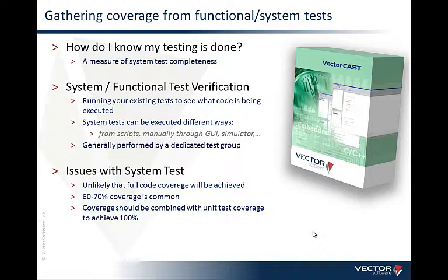The idea here is that the completed executable is loaded down onto the target, and the flow of execution is stimulated through the real inputs that the target has, some kind of sensors or switches, and the code is exercised to conform to the test cases, and the outputs from the system are observed. So whether they are voltages appearing somewhere, whether they are actuators that are being operated.